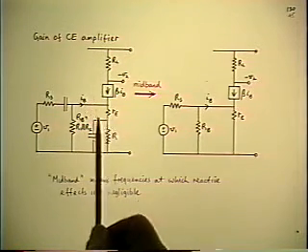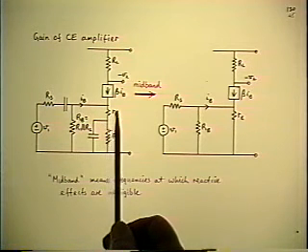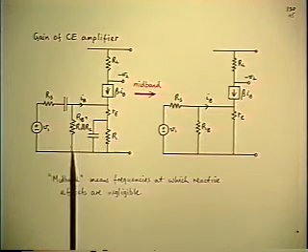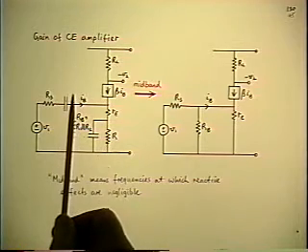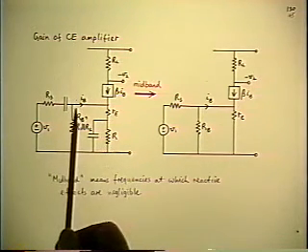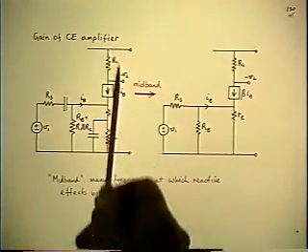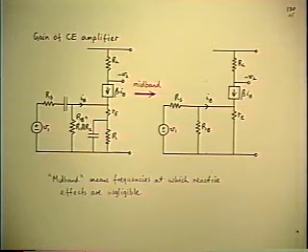So that's about the simplest possible model you could use to represent the bipolar transistor. Outside of that, RB represents the bias divider, actually coming from R1 from the supply to the base, and R2 to ground, but since the power supply is the same as AC ground, those two resistors R1 and R2 can be put in parallel immediately.